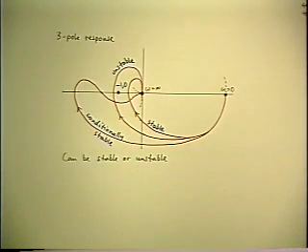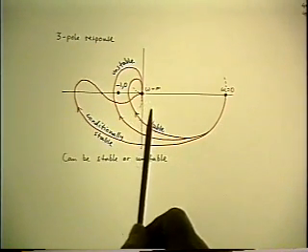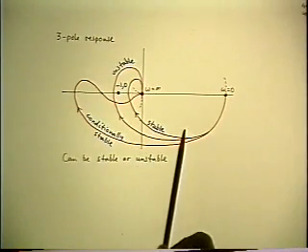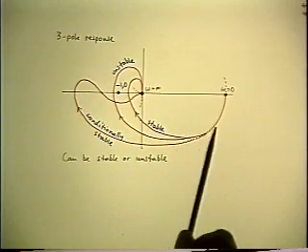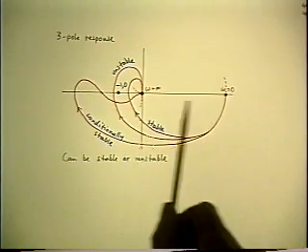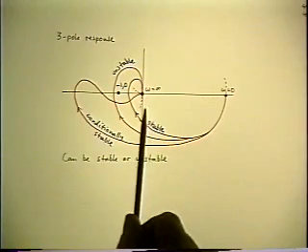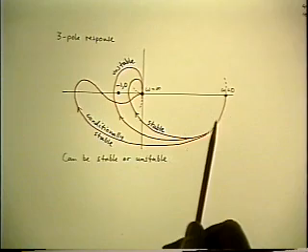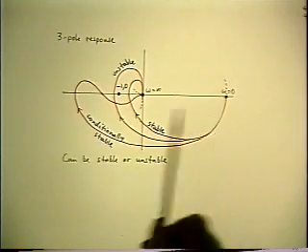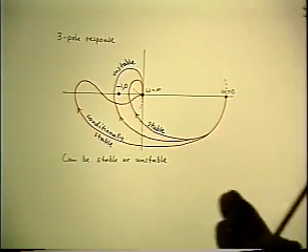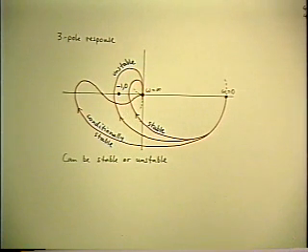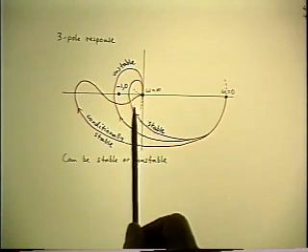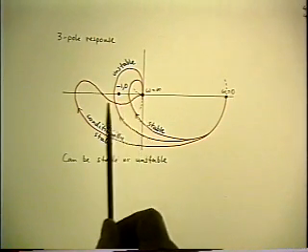So the conclusion is that a three-pole and up system is stable or unstable depending on the particular values involved, and typically would be stable for low values of gain and might go unstable for higher values, since higher values of the T0 or whatever the parameters are of the loop gain obviously make the contour get bigger. So typically a three-pole or up system might be stable for low values of loop gain, but might go unstable at higher values.